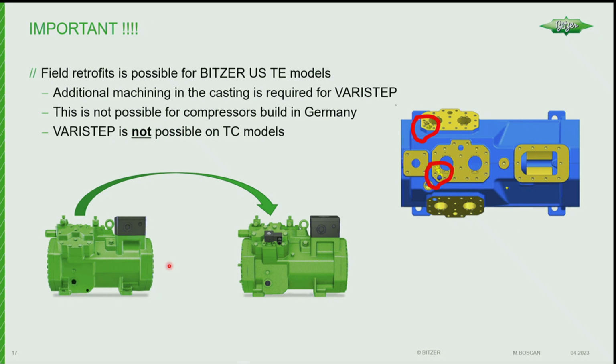All right, so one important thing to know is that the TE series is our latest series for CO2. What's the lowest capacity you could go on a VFD? 30 hertz, 25 or 30 hertz, depending on a 6, 4, or 2. You're able to go lower with that module to get more capacity. Yes, exactly. So basically 50% on a VFD from 60 to 35 hertz. You can overspeed on a VFD, so in theory, if you go to 70 or 75, it's going to be a little lower than 50%. But this does go lower than the VFD.